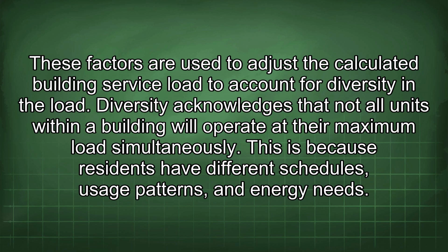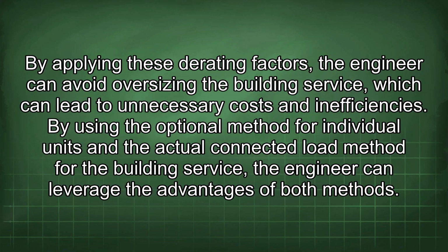Diversity acknowledges that not all units within a building will operate at their maximum load simultaneously. This is because residents have different schedules, usage patterns, and energy needs. By applying these derating factors, the engineer can avoid oversizing the building service, which can lead to unnecessary costs and inefficiencies. By using the optional method for individual units and the actual connected load method for the building service, the